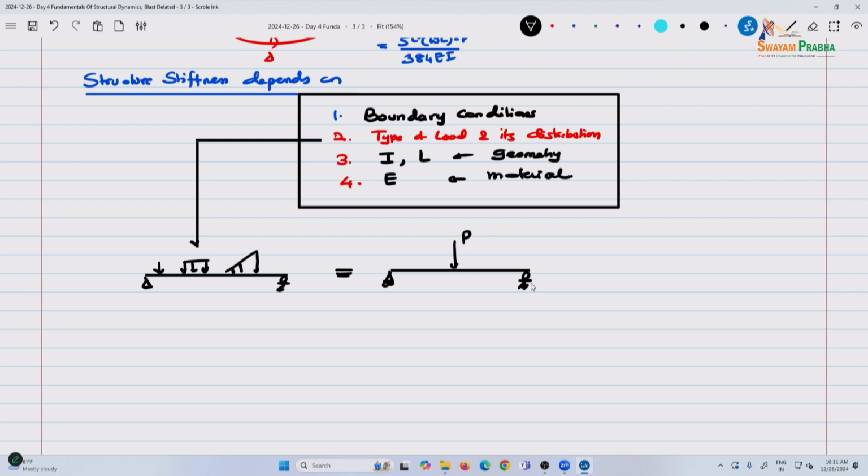It's better to get into a point load. You can try what the stiffnesses are coming from both cases, and that's a good exercise for you to try. Put an equivalent and then convert it to a point load and see if the K values are different. Since we have a spring stiffness model, you get an equivalent load that creates the same moments and shears.